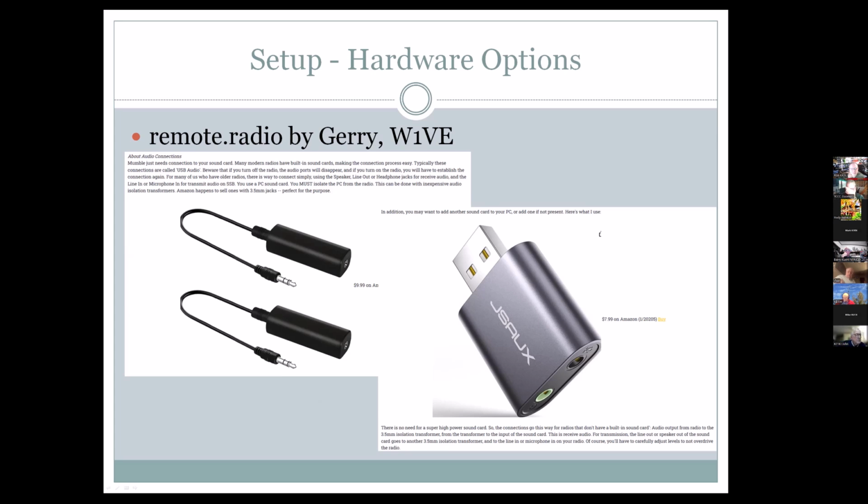But again, they don't need any additional wires to bring the audio in and out. Right. Also, listening to your comments on digital, that's the other beauty of it, because the audio for the digital comes from the USB codec. You can actually plug your headphones either in the SO2R box or directly into the radio, and you can control the volumes independently.